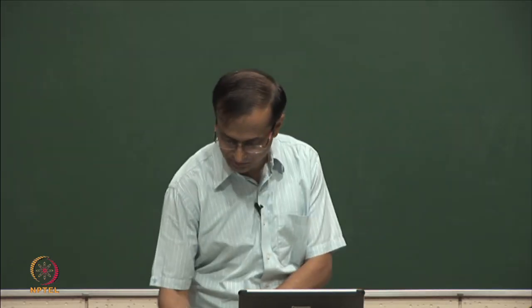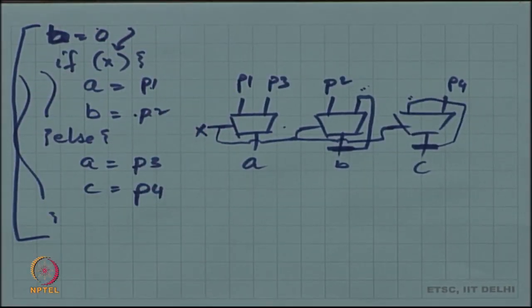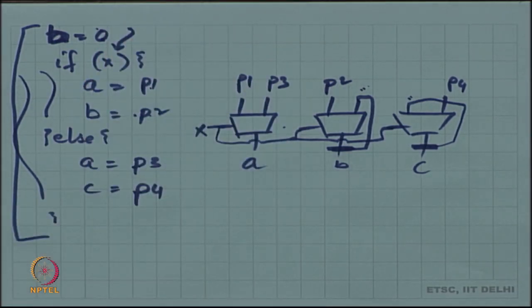So, this whole thing could be inside a process and it is fine. We do not rely on remembering the value of B from the previous triggering of the process. Everything is still determined from this triggering, which is this function is computed. It is an assignment or it is a more complex function. It is computed right there. That would lead to a combinational logic. If you rely on remembering the value of B from the last time the process was invoked, then you need a memory element.